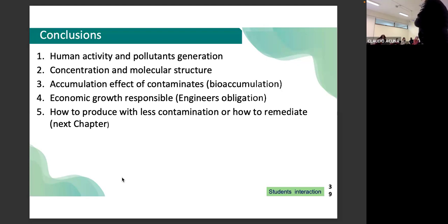When you have, for example, precipitation of arsenic, any fine particles, you end up with 90% water. So if you have a sludge with 90% water, fine particles, you cannot remove it. This is called capillary retention. You can use thermal processes, you can use electro-osmotic dewatering, but this is a big issue.